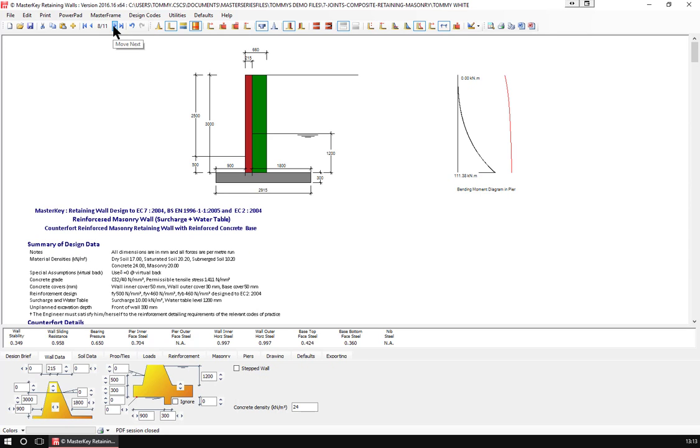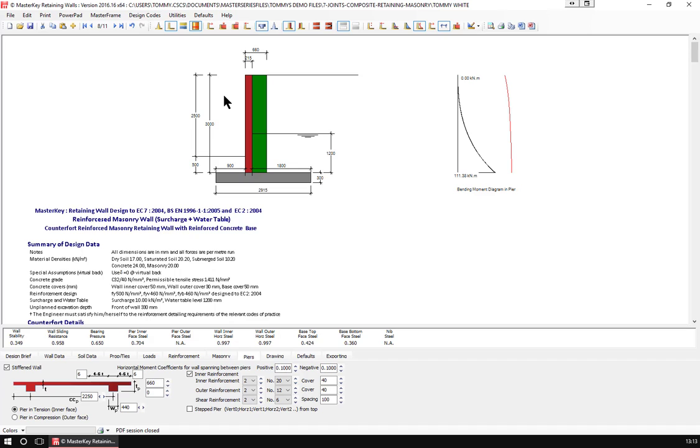We now come to something that's very nasty, very horrible. I don't like it at all. It's there, it's doable. What we're talking about is a wall that's masonry with counterforts. With counterforts, we can design this wall to be a lot thinner. The counterforts are 440 wide and it's 660 wide at the base, and they are at 225 centers.